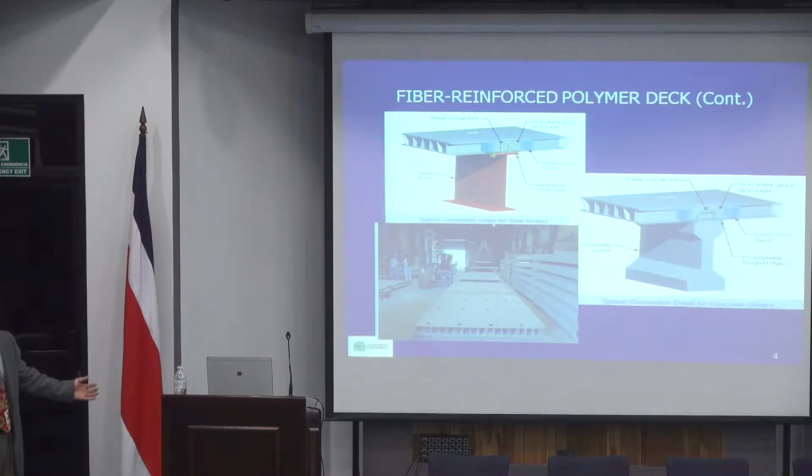The reason for 3 meters is that they can put it into a truck easily to transport. They also have some holes on top. These holes will be designed to match whatever shear studs, or if it's concrete, where the shear reinforcements are. So that will be the detail for either steel or concrete structures.